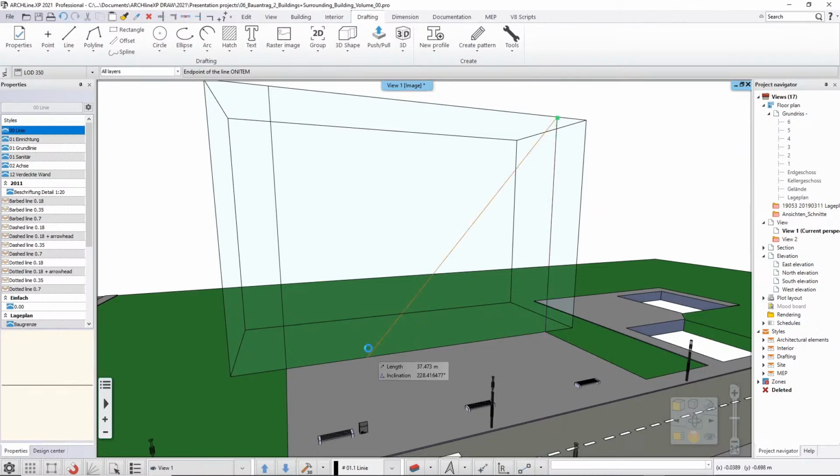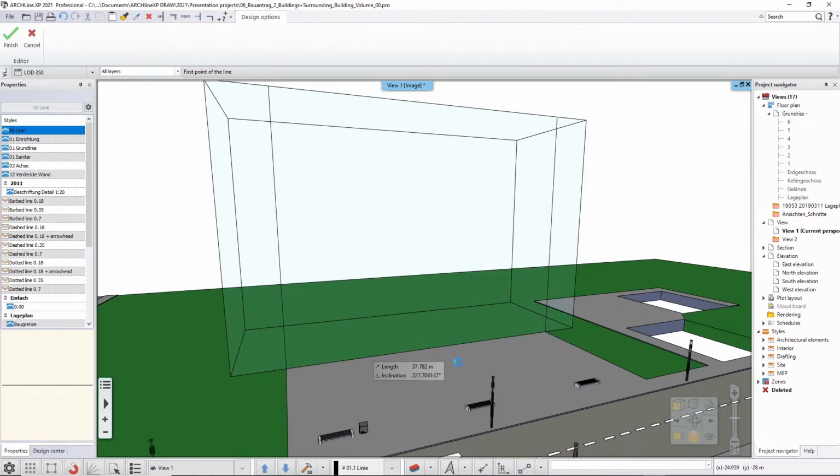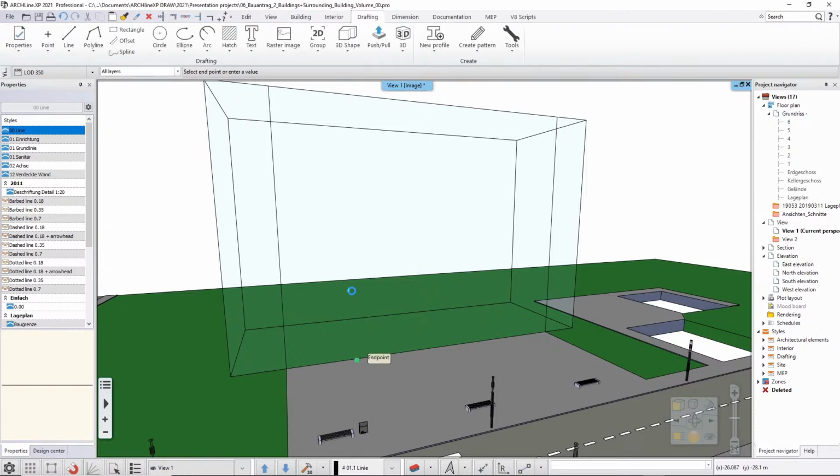I would also like to create a nice entrance part here, so I will create something like that. I start from this edge point and go upwards. This time let's just use a real world value, like 6 meters or so. Horizontally, I think double this would be fine, so let's say this is 12 meters. Then I go down towards the floor, and I either close this like that, or I just use the value 6 meters.